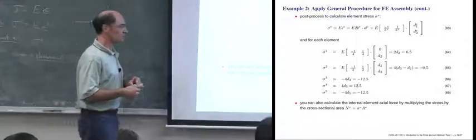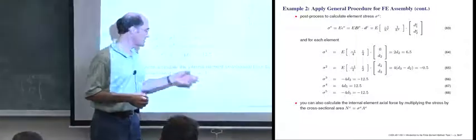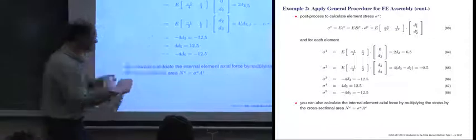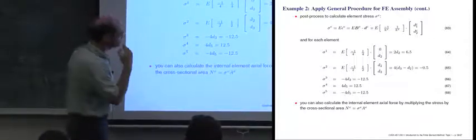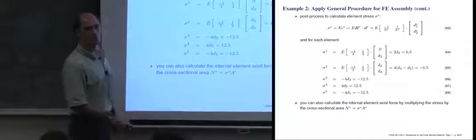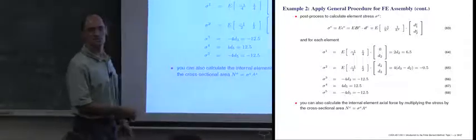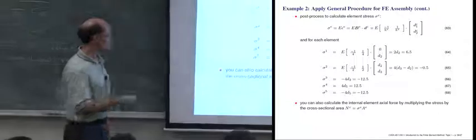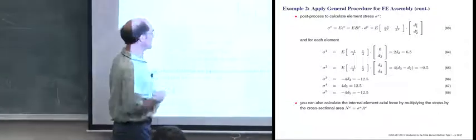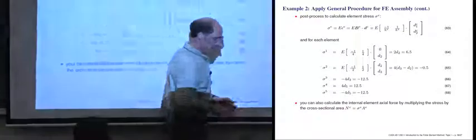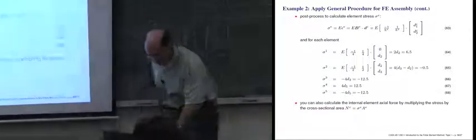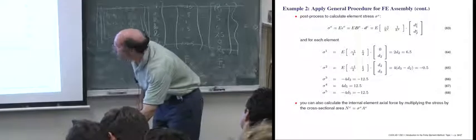However, what we'll see, and it's more clear in the lab when we get to the Abaqus tutorials, is the key point: as we make these elements smaller and smaller, you'll start to see a convergence to what the solution really should be, the exact solution. This mesh is rather coarse, but as we make the mesh finer and finer, we'll eventually converge to the exact solution, if it's linear. Of course, if it's nonlinear, all bets are off.